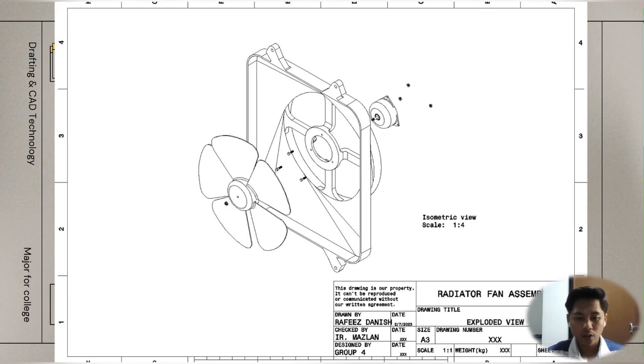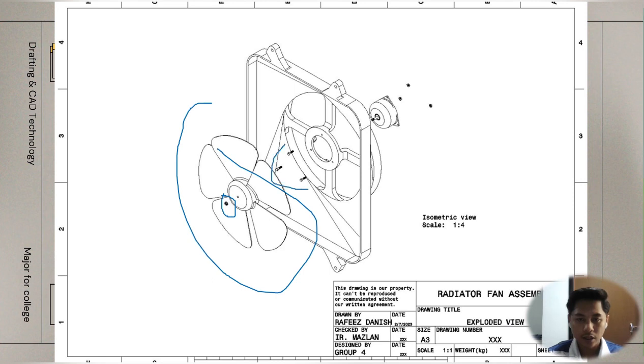Okay, so here is the example of our product which we have created the exploded view. So here there's a nut, the fan, all right. Then there's three screws, the fan case which attached to this area, the fan motor, and also the nuts. We have arranged and set the distance using the enhancements in Catia.